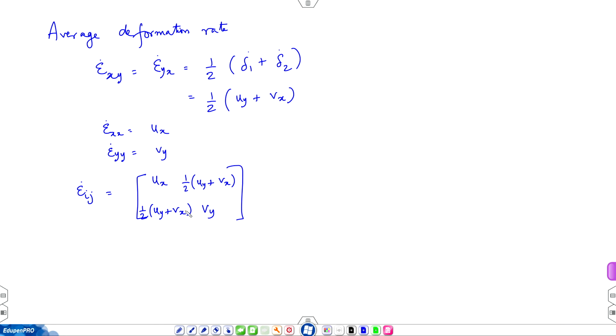I will leave it as an exercise. If you are interested, you can show that the expression for epsilon dot i j in coordinate free form is del u plus del u transpose. So, we are out of time. So, on Monday we will talk about the stress strain rate relationship for a Newtonian fluid. Okay. That will then connect stresses to the flow field.